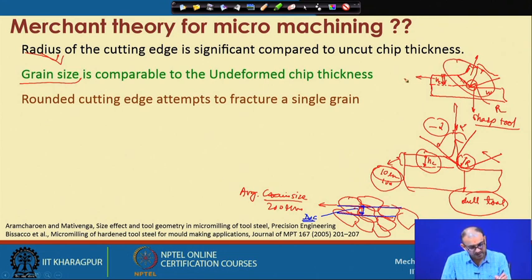It may be 0.5 millimeter, up to whatever is the capacity of the machine. You can even start with 100 micron, and go up to millimeters very easily in conventional machining. But here we do not talk about millimeter size, because the material we want to remove has a very, very small thickness. We do not want to remove more material from the workpiece because of the scaling of the part.